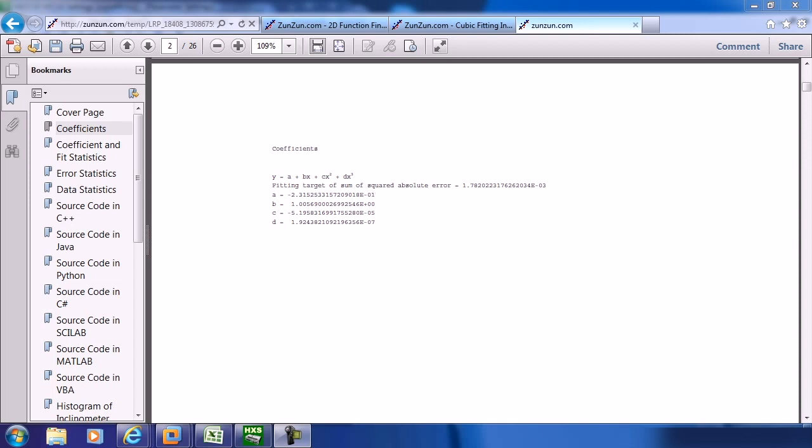And now we're going to work through the second example, which was taking a reading from an inclinometer on a concentrated solar thermal power tracking system and correcting it for gravitational, weight lag on the actual heat transfer fluid receiver. That's the fluid pipe that runs in front of the collector, where all the light energy heat gets concentrated, and heats up the oil to then generate steam in a steam plant. So what I'm looking at here now on the screen is just the PDF file that ZunZun allows you to generate.